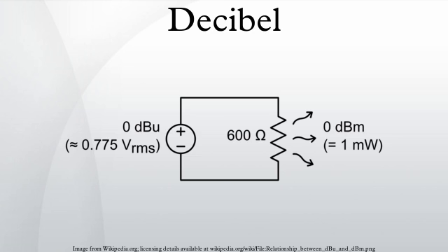dBm, decibel milliwatt: power relative to 1 milliwatt. Traditionally associated with the telephone and broadcasting industry to express audio power levels referenced to 1 milliwatt of power, normally with a 600 ohm load, which is a voltage level of 0.775 volts or 775 millivolts. This is still commonly used to express audio levels with professional audio equipment. In the radio field, dBm is usually referenced to a 50 ohm load, with the resultant voltage being 0.224 volts.